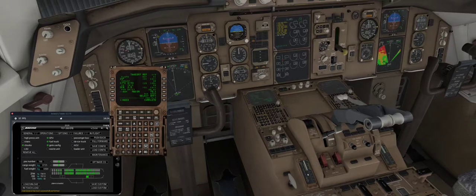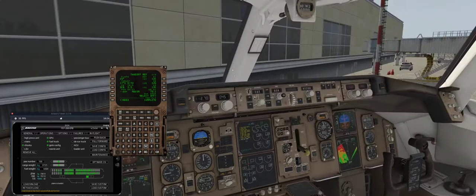So you'll see I'm moving the stabilizer trim right now, setting it to 2.9. That's probably 3, so we'll say that's 2.9. And then you want to click each one of these. That's like saying, okay, I'll take your recommendations. And the V2 speed is 131. That's important. That's when you rotate back. And you notice that it got populated here. That happened when we did all of this.